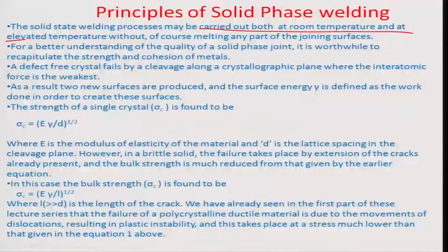also at an elevated temperature, but without melting any parts. Okay. So, these are still solid surfaces, they do not lose their integrity, and you can basically apply pressure as well as heat here to perform the welding. So, for a better understanding of the quality of the solid phase joint, it is worthwhile to recapitulate the strength and cohesion of metals. Okay.